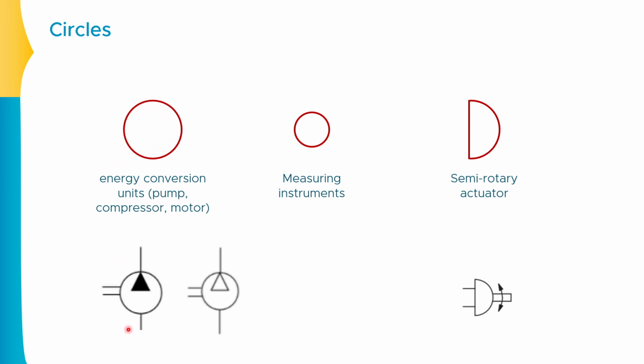This is the symbol of the pump, as you can observe. This is the inlet line. This arrow represents the hydraulic fluid, and this is your outlet line, and the double line shows that this is a shaft connection, or say there is some mechanical connection available here.